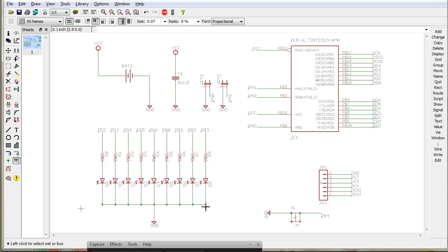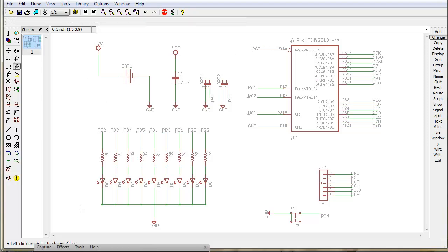Now I could actually split these off and put them onto their own schematics, but I don't think there's really any point on here. So at this point, we've really laid out everything we can here, and now what we can do is look at what we could add. The text command is going to let us add text, obviously. You can set the ratio, which is the thickness of the letters, and then the size, which is the dimensions. And put a little thing there.